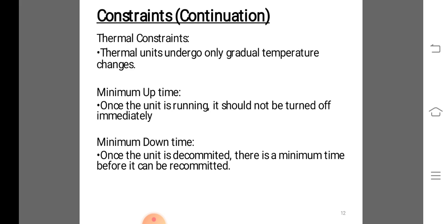In addition, because the temperature and pressure of the thermal unit must be moved slowly, a certain amount of energy must be expended to bring the unit online. This energy does not result in any megawatt generation from the unit and is brought into the unit commitment problem as a startup cost.